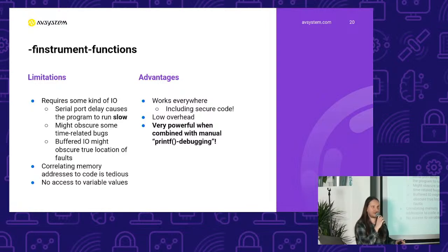I said that you can correlate the last function that gets executed, but this is not always true. If you have, for example, asynchronous I/O, then the thing you want to output on the serial port might just get buffered, and then your board will reboot before the buffer gets printed out. So this is not a 100% always working solution, but this is still really powerful. That can be helpful in many situations, especially when you don't have a possibility to use a proper debugger.